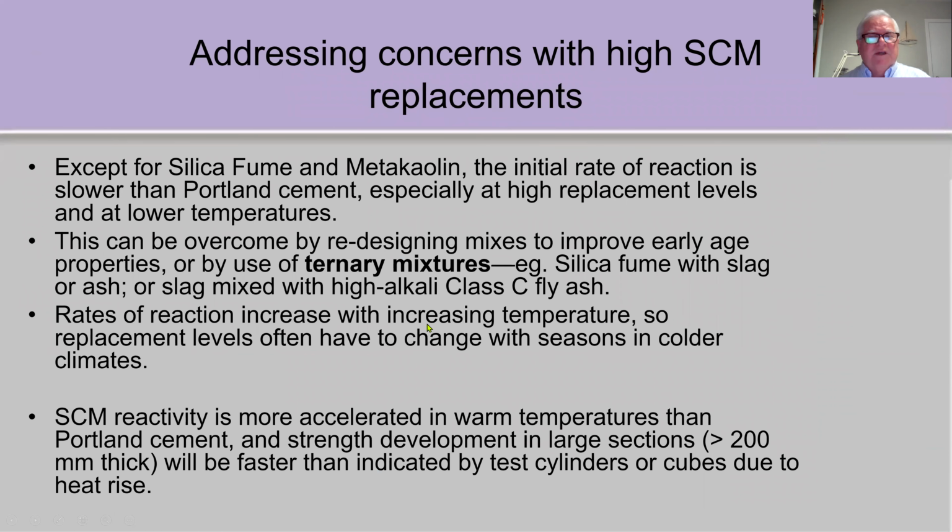Now, people worry when we get too high on the supplementary cementing materials, not so much with silica fume and metakaolin because they're much more reactive, but with low calcium fly ashes and to some extent slag, you can get slower early age strength development. So that requires redesigning the mix a little bit if necessary to compensate for that.